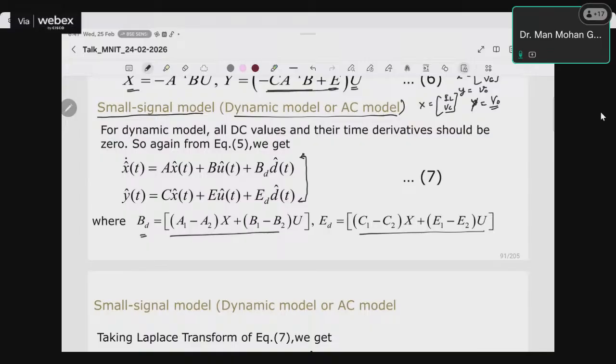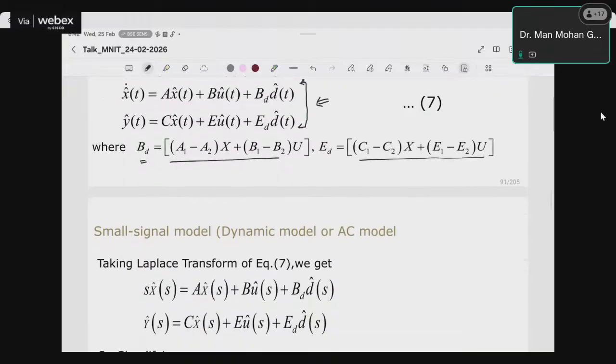It's in time domain. If we have any technique which can be used for time domain systems, then we can directly use this particular model for controller design. But if we need transfer functions, we have some techniques which are useful for linear controllers, then we go for its Laplace transform, right? So what we do, we take its Laplace transform.